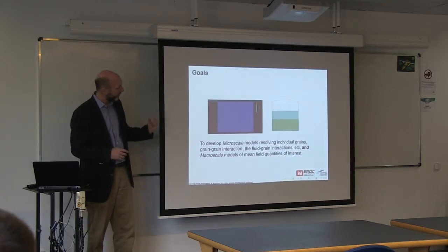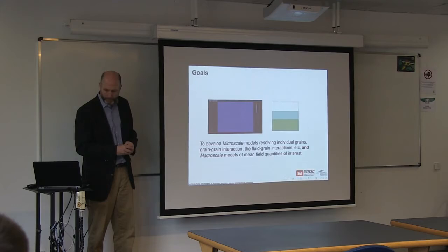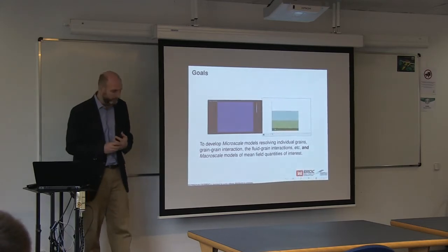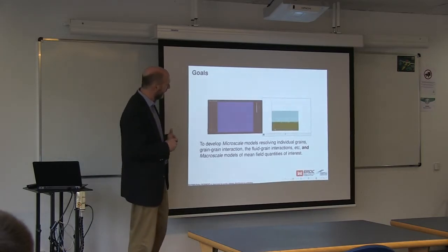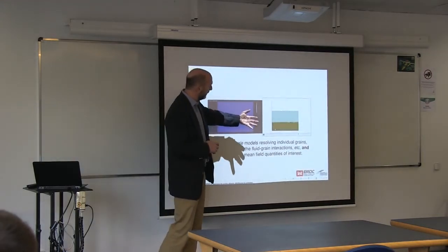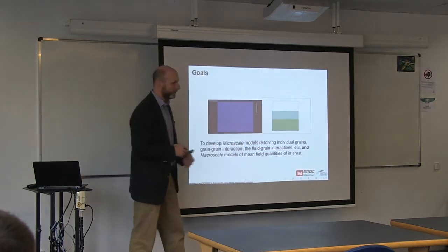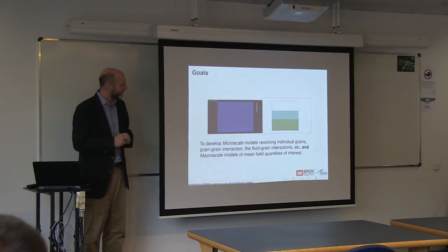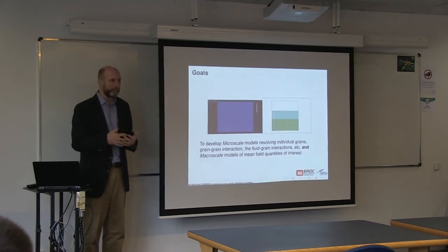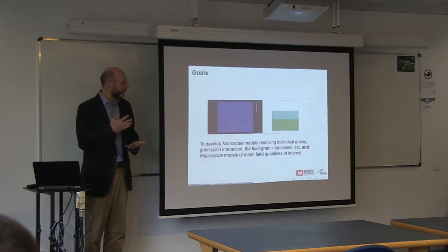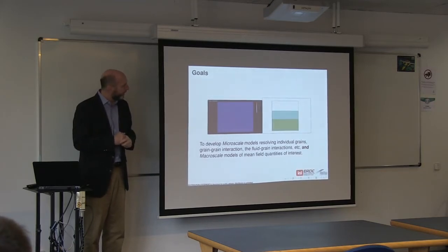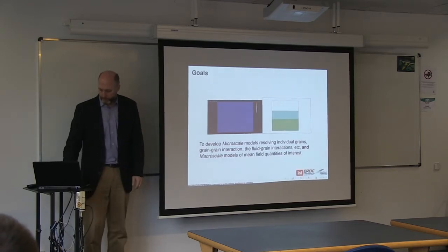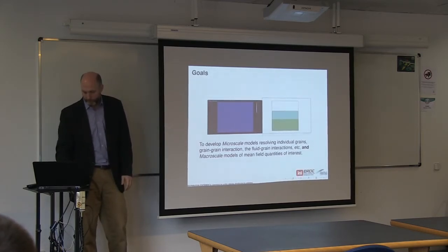So we want to use these microscale models in sort of our standard multi-scale modeling approach to derive constitutive relations for volume average models. So in this case, I'm just showing a similar issue where I've got a diffuse granular material that I then allow to settle into the bed. And so we're trying to work at both scales. Of course, from the computational side, a lot of the tools are similar. We need fast Navier-Stokes solvers that are robust and accurate. And we need to deal with multiple phases. So we can share a lot of the infrastructure between these two scales.